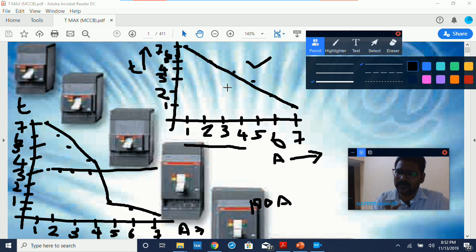For example, if we take a 400 amps breaker, one variant will be of electromagnetic type, one variant will be of fixed type, one variant will be of adjustable type. So 2-3 options are available, and we can select the breaker based on the customer's requirement. In ACB, we don't have individual variants. In a single breaker itself, we can choose whether we want PR121 or 122 or 123, whether we want LI or LSA or LSAG. ACBs are completely customizable, but MCCBs are ready-made only.